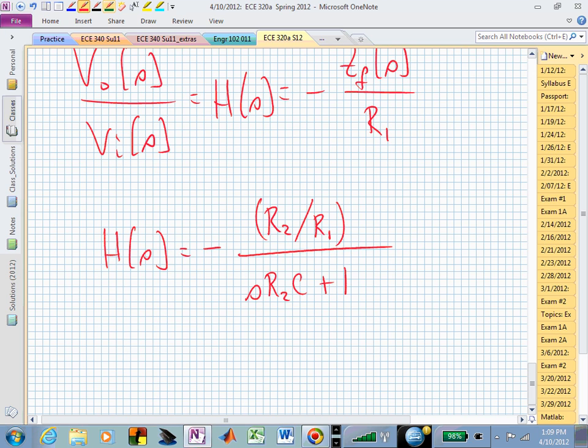And so what is our cutoff frequency? Where does this transition occur, or where do we approximate it? In this case, what's the order of this low-pass filter? 1. We only have one pole, right? S to the 1. We have one pole. This is a first-order low-pass filter from that op-amp circuit. We built a first-order low-pass, so now it's an active device. We have an active filter.